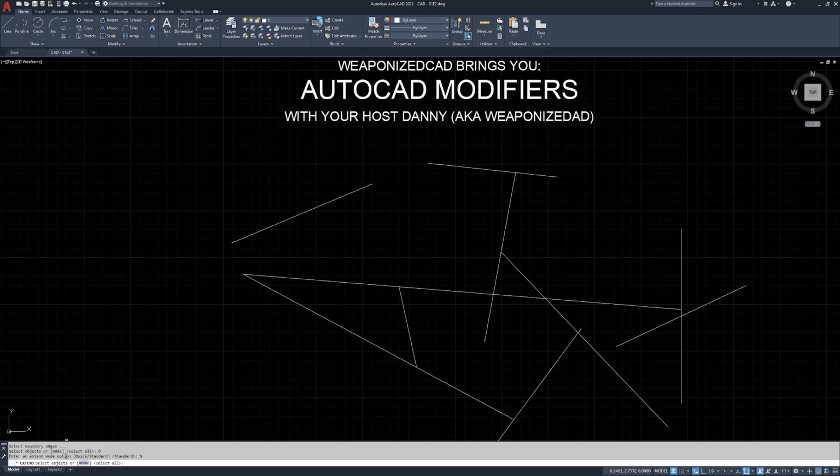With it set to standard mode, it's going to ask me to select objects. Let's say I want to select this as my extend line. I'm going to right click, and you'll notice it says path does not intersect with the bounding edge, which means that when this line is extended out, this line isn't going to touch it.